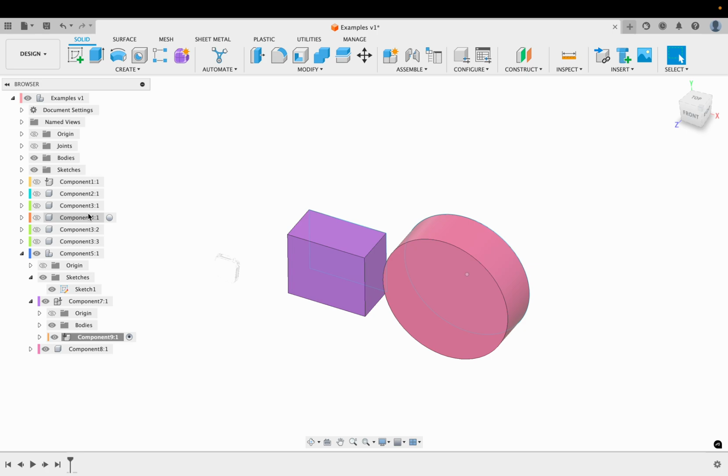And then when you're done with this head cup, you just mirror the entire thing. And then you do some modifications to that mirror, like you can take off the buttons and things because you don't want buttons on both sides. Maybe you need to, yeah, different ways of doing that, but you mirror and then you take out some features. That's probably easier than modeling separate right and left. I would not do that. I would make the complicated one first, and then I would take out features to simplify it to make the other side. Okay?